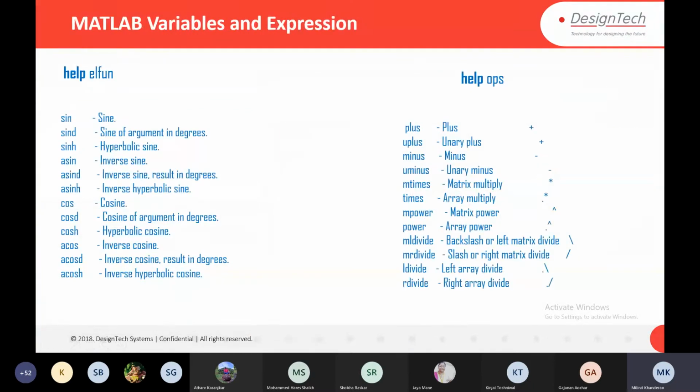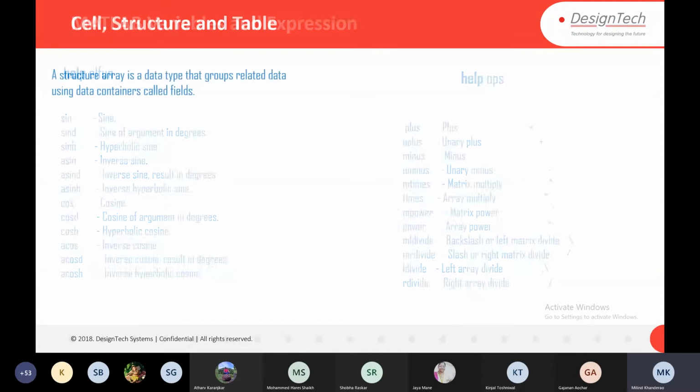Now MATLAB variables and expressions. MATLAB supports elementary functions, let's say sine, hyperbolic sine, and also cos. Then the arithmetic operators like addition, multiplication, subtraction, power, and the dot operator. The dot operator stands for element-wise operation.